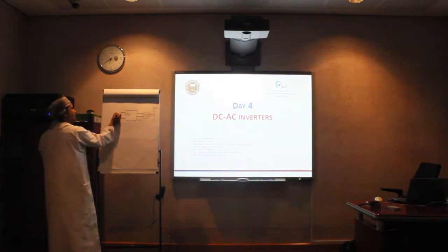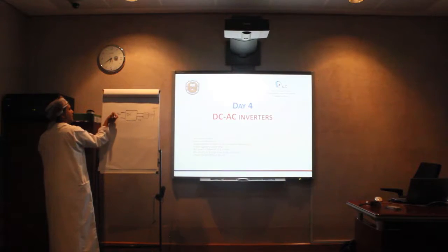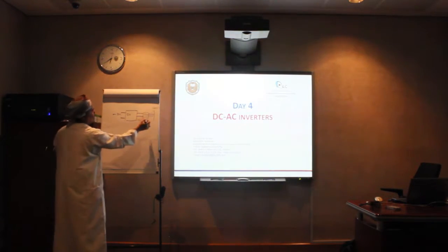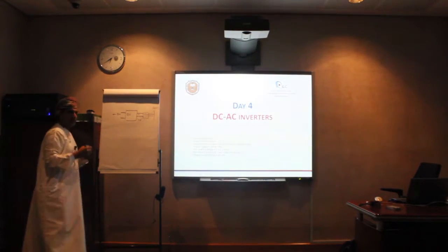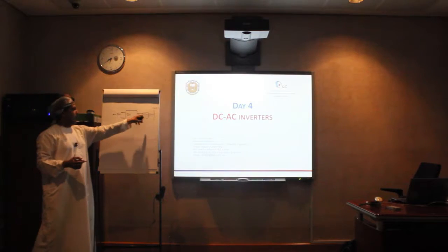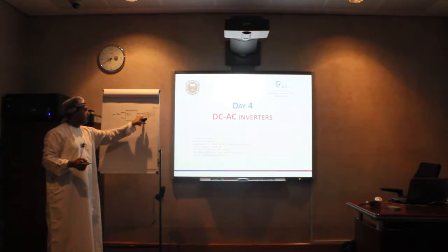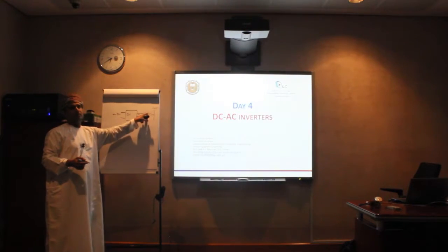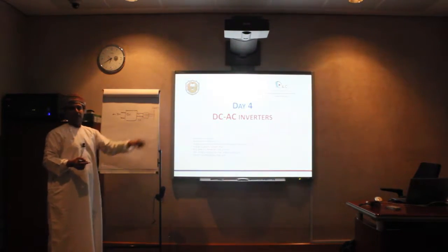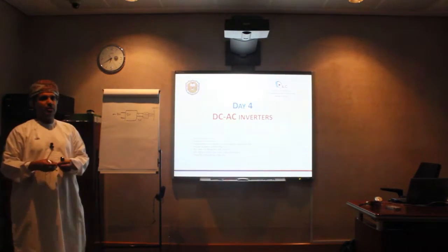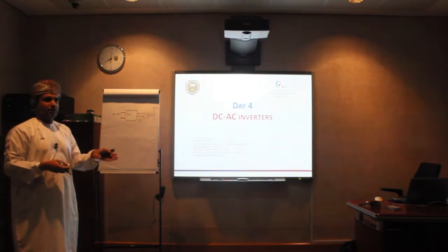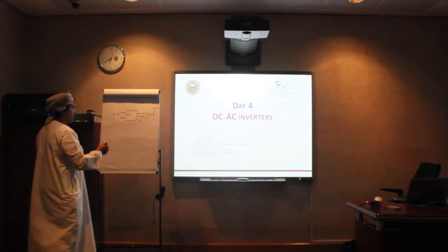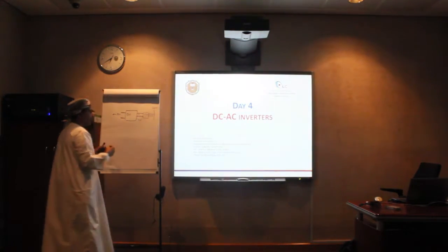So that means if I have a DC which is coming from a boost converter or from whatever, you can get this DC to an AC, and this AC at this place here is distorted, and then again a filter is used to filter the harmonic components or the noise, and then you will get the fundamental component, which is a sinusoidal waveform with the required standard, like 50 Hertz or 60 Hertz in some countries. And the voltage level here should also be controlled depending on your system.